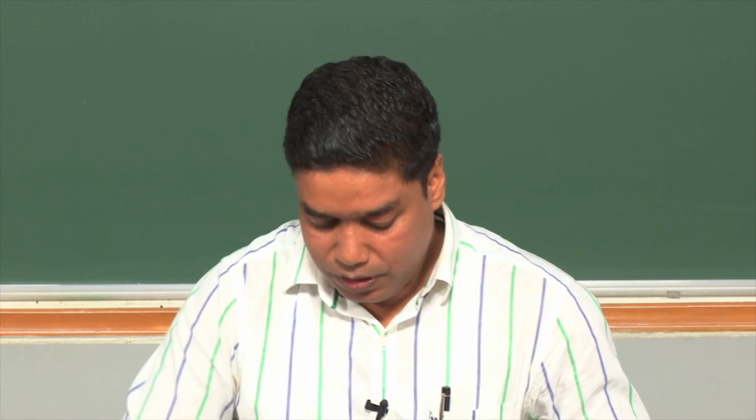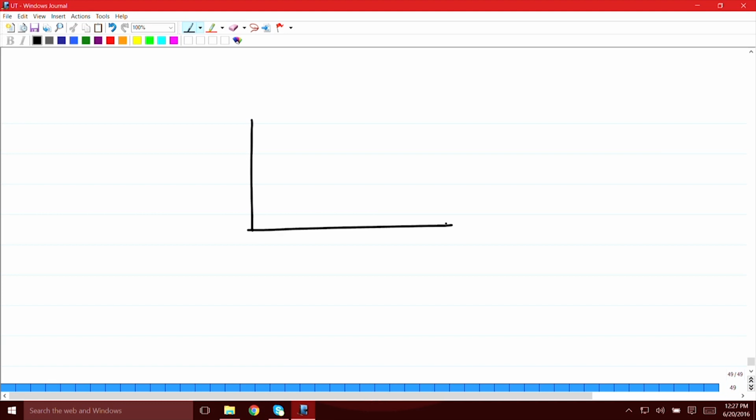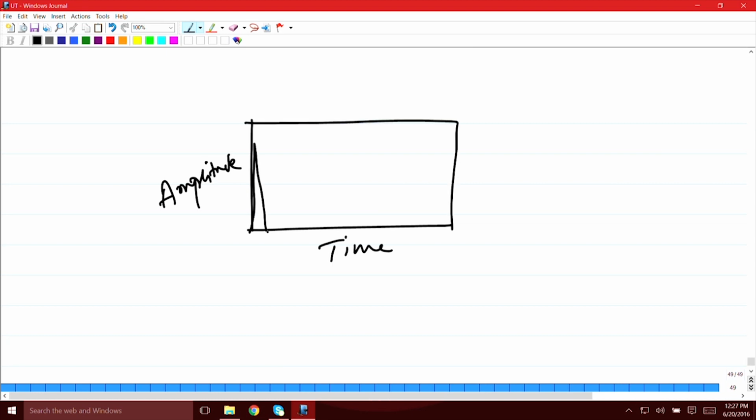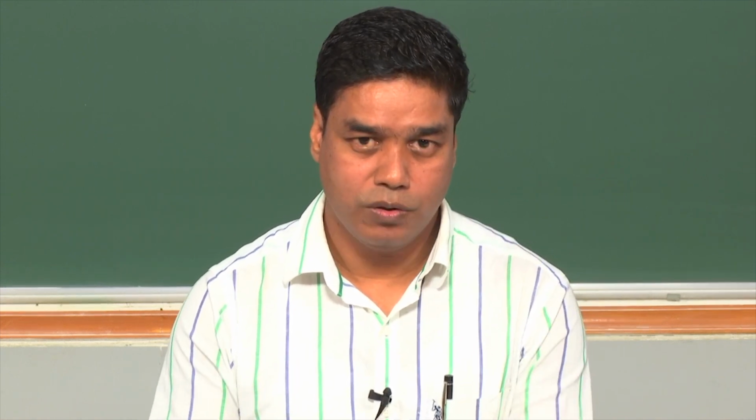Because this time base that you have in the display, this is the initial pulse, this is the back wall, and the x axis shows you the time at which the echoes come back to the probe.